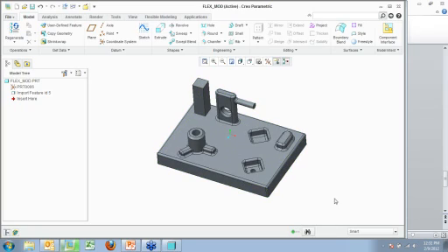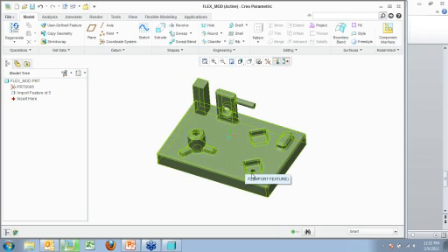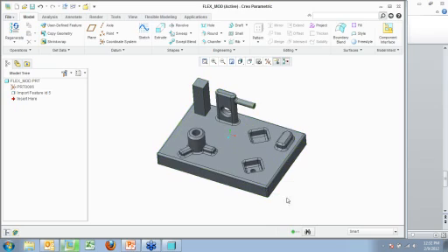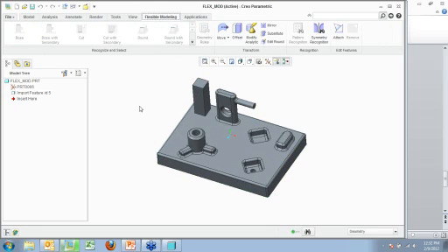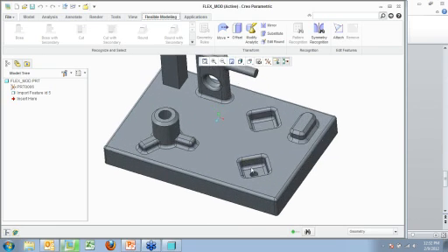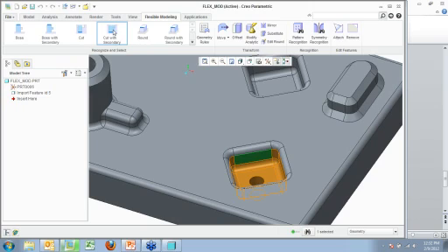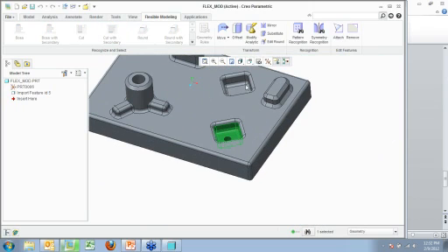This is just geometry. So if I'm doing mold designs or something, and I get something from one of my vendors, and I realize, oh well, this hole's not in quite the right spot. I need to turn this hole by 15 degrees to get the part that I actually want. Then I can come in, select this face. We'll say cut with secondary features.